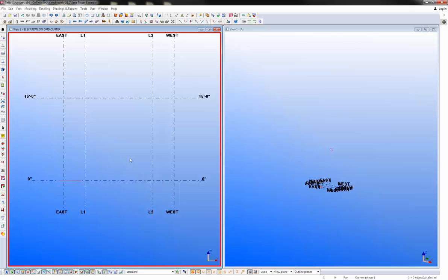First thing I'm going to do is come in and set out a landing. So this is something that I would normally have done already. Basing off of my 11-inch width, 7-inch depth, average tread that I'm going for, I would have simply laid out some construction lines or just used a calculator to figure out where I wanted this to be.